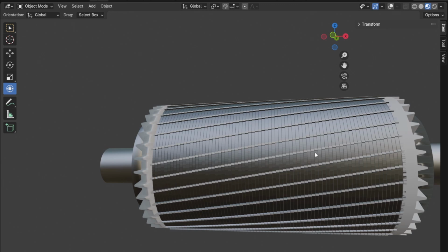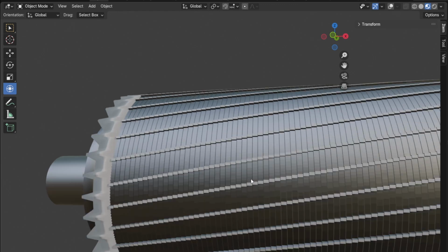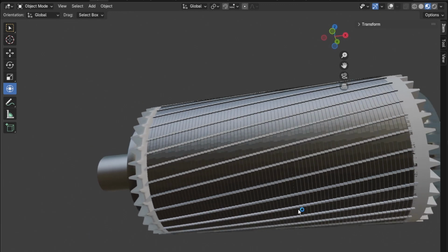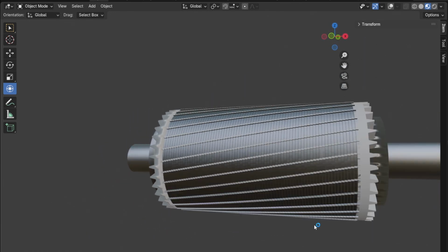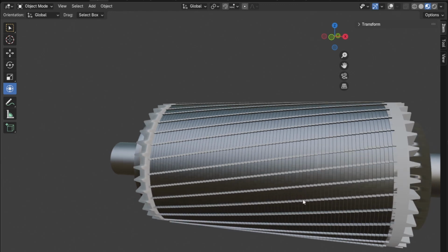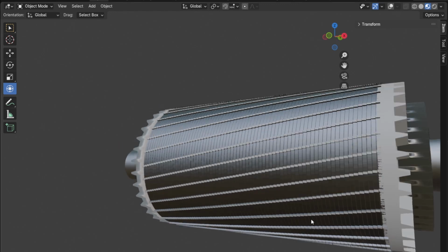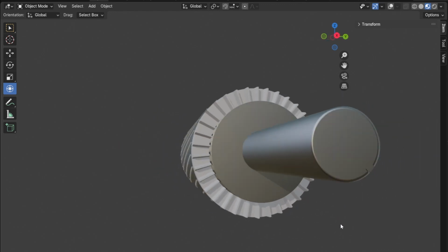And these bars, like I said, are also conductive. It is highly important that we understand that. Anything that is a lighter shade here is conductive. Anything that is darker is not electrically conductive, but it has a low magnetic reluctance. And so it's very easy for flux to course through this material relative to the air that's around it. And so that's pretty much our rotor right there.